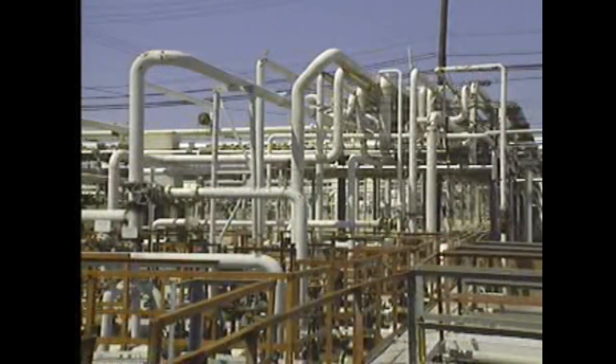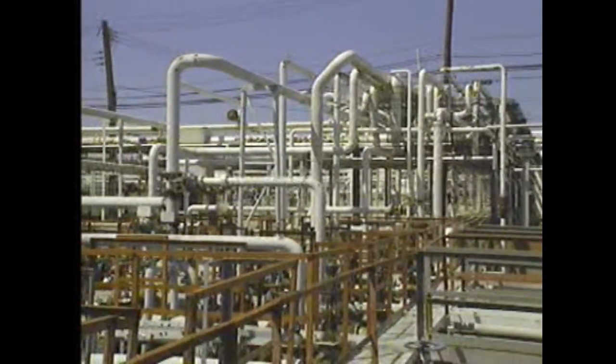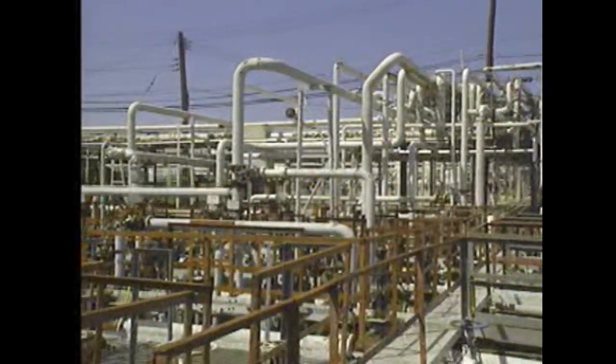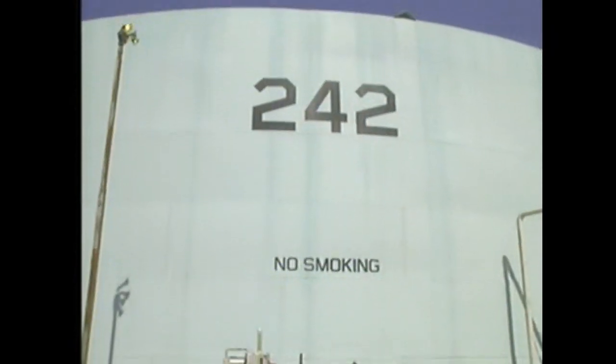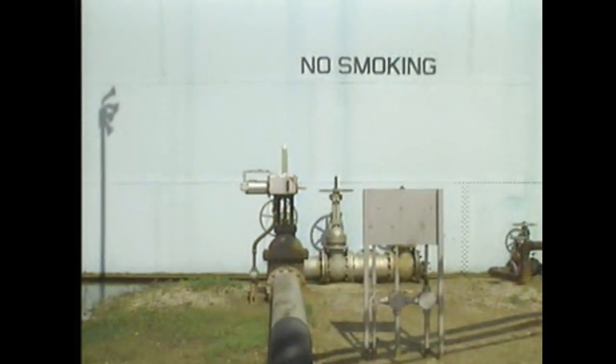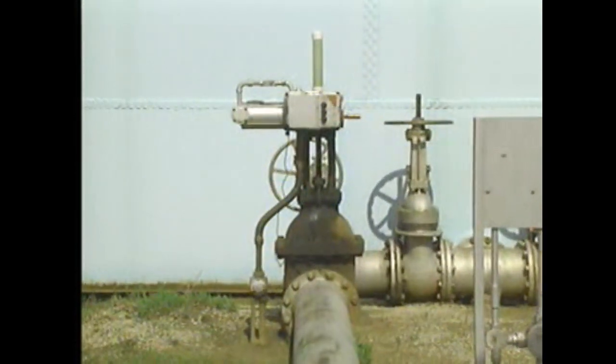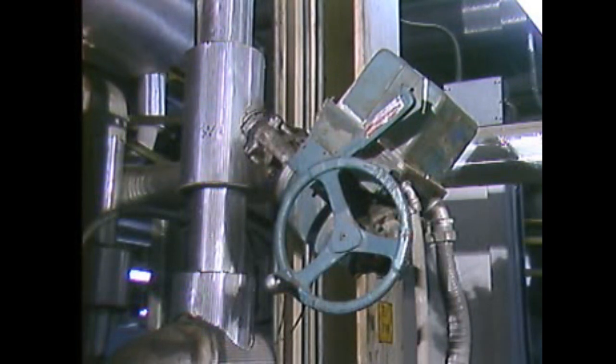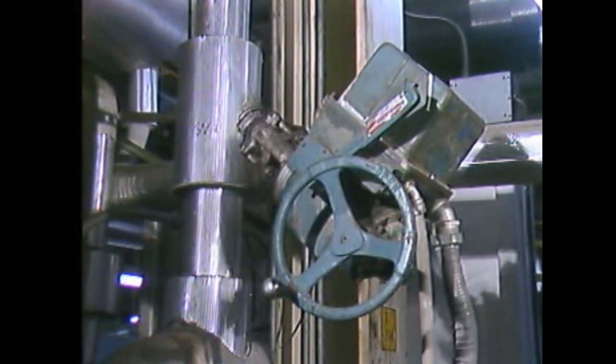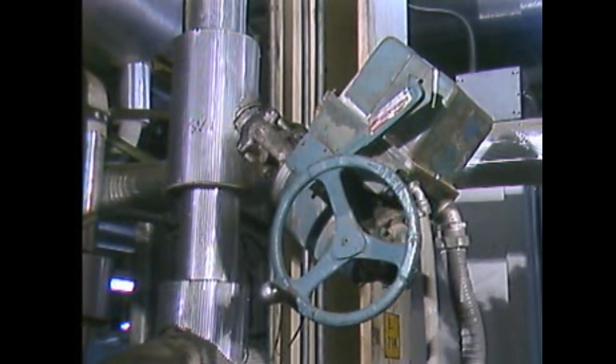If you perform maintenance on a system that includes pipes and valves, you need to know how the valve operators are constructed and how they work. Although there are many types of valve operators, we'll be focusing on the motor-driven types that are used in many large piping systems. In a high-pressure fluid system, several tons of force may be exerted on a valve stem. It wouldn't be very practical to try to operate a valve like this by hand, especially if the valve has to be positioned frequently. In this situation, a motor-driven valve operator can provide the force that's needed to open or close the valve.